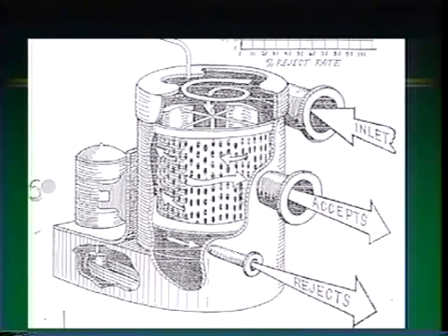Okay? Now the other thing that we can see here is that we've got these foils, and in this case these foils are mounted on a rotor that holds them, and they are very close to the face of the screen. You see we've got a motor here that runs a belt that actually turns these foils. Now the foils have two purposes. One is to keep the stock moving and spinning. That's useful in our screening operation. And the second one is even more important, and we'll talk about that in the next slide. So that's a schematic of a cylindrical screen.